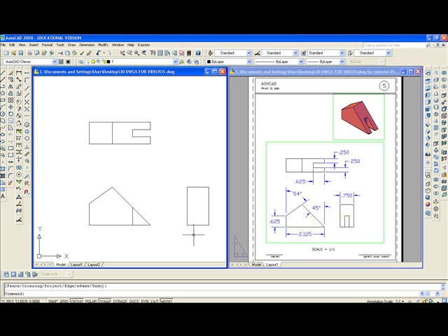Now we have to complete the right side view. And so we're going to O enter, 0.25 enter. Here to here, and move that over that way. Then draw a line from this point here. Then fillet it with radius 0, that area.